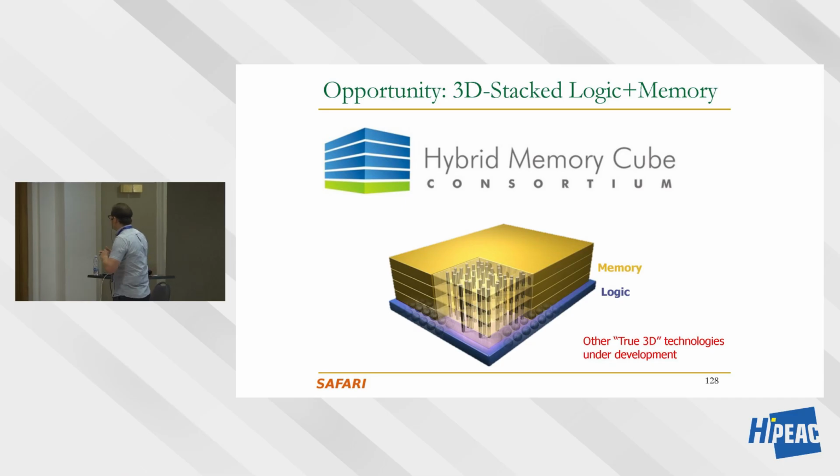So when we first started doing the research, we were very interested in 3D stacked memories, and we believed, and I still believe, 3D stacked memories are a good substrate for doing computation. Here you have a logic layer, and on top of that, you have many memory layers. HBM, high bandwidth memory, is one example. It's used as 2.5D stacked memory today, but going forward, there's no reason why it cannot be completely 3D stacked. I think it's going to happen in HBM4, for example. They're going to have a true logic layer underneath memory layers, and there will be a lot of opportunity for doing computation.